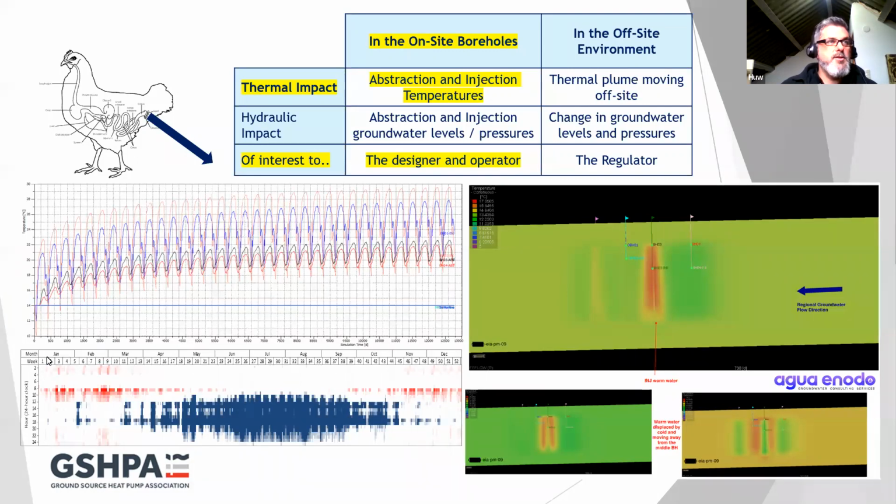So you can see that in January, at the start of the year, we've got some small heating load in the morning to warm the building up, and then by the time we get to May, we've got a predominantly cooling load that's strongest in July, August, and June, and then recedes back to December with some heating load. So these are the loads that we convert into flow rates and delta T's for the groundwater model, and our prediction here.